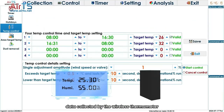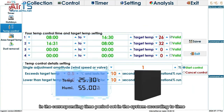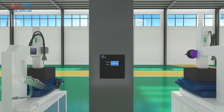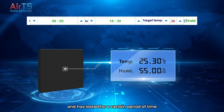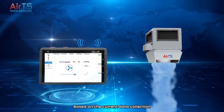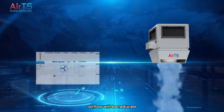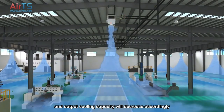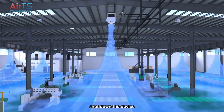The temperature data collected by the wireless thermometer is compared with the target temperature value in the corresponding time period set in the system according to time. If the data collected by the thermometer is lower than the target temperature set in the system and has lasted for a certain period of time, the system will send real-time commands to the device. Based on the current data collection, decrease the fan's frequency. By reducing the fan frequency, airflow will be reduced and output cooling capacity will decrease accordingly. Once the frequency reaches its minimum set value, shut down the device.